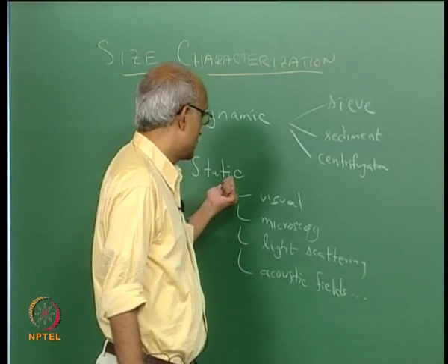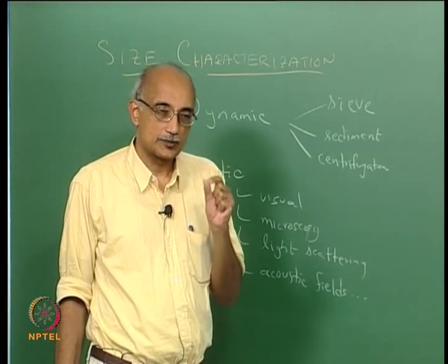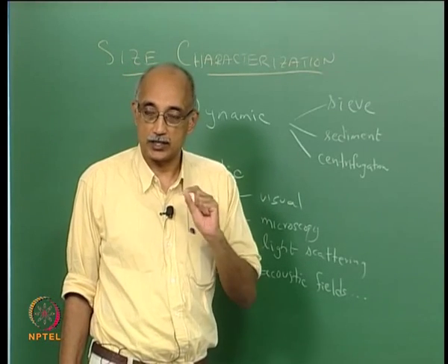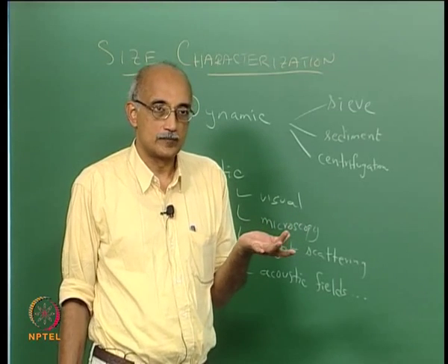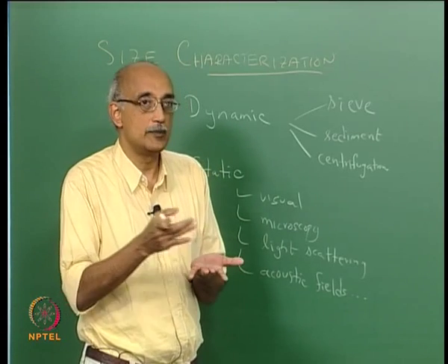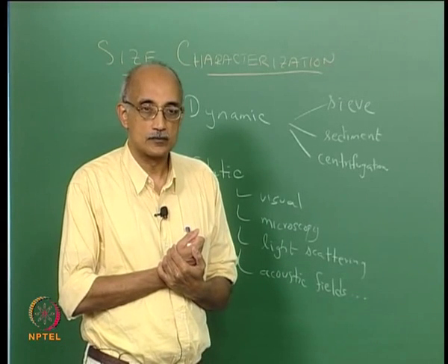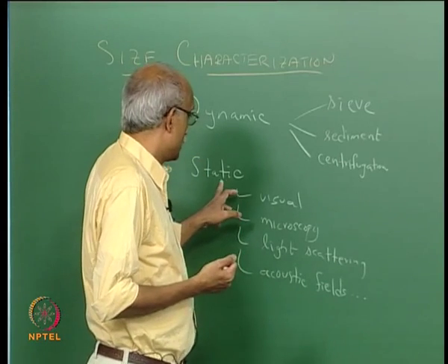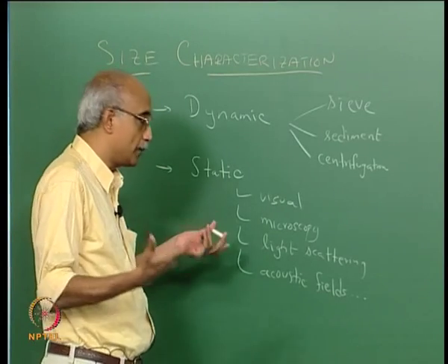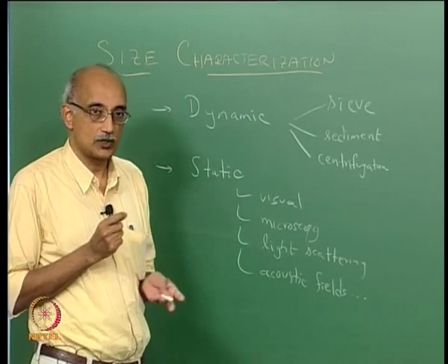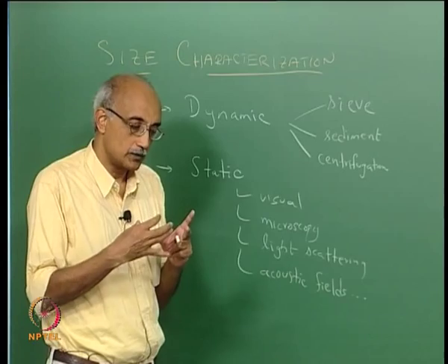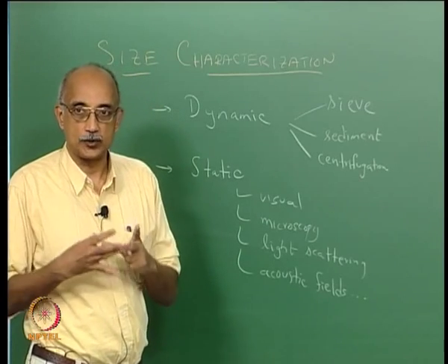Now, that is not so easy to do, because especially as particles get finer and finer, they want to keep moving. Their diffusional velocities are very high. If you talk about a nanometer size particle, it is never sitting in one place. Even within a second, it could have moved millimeters, depending on the size of the particle. So, static analysis sounds like a very powerful and more informative way of doing size analysis, but the first challenge you have to deal with is how to collect the particles onto a substrate from which you can then analyze the size of the particle.